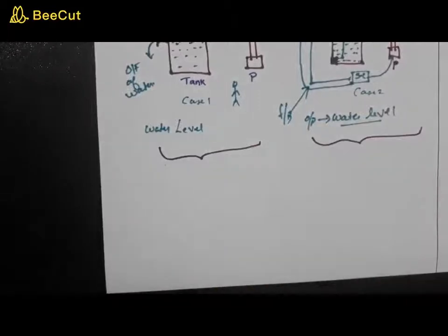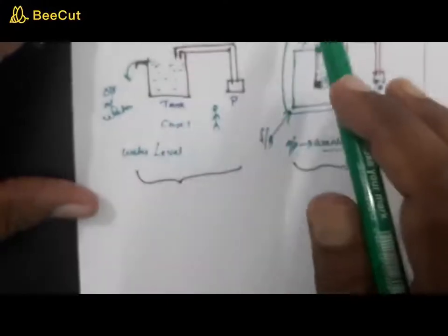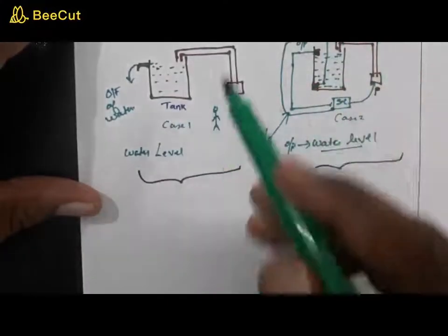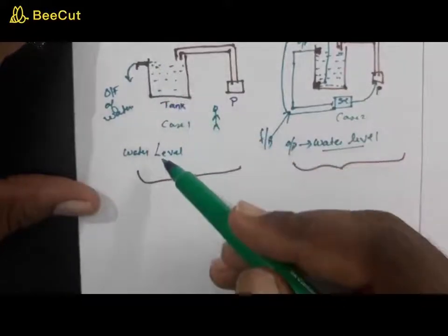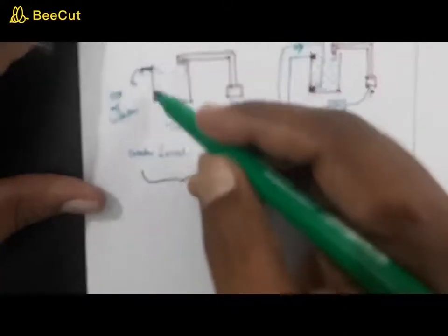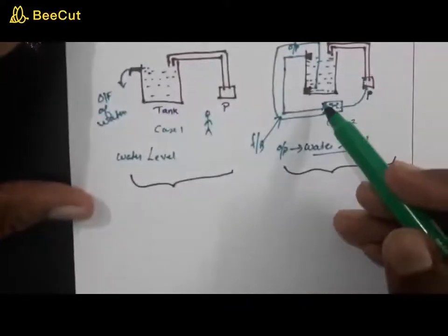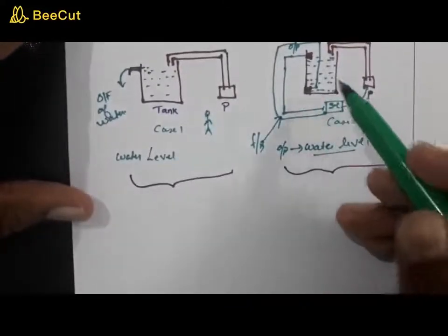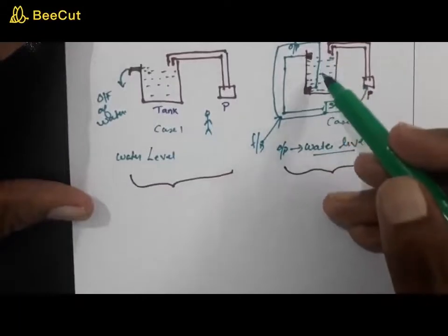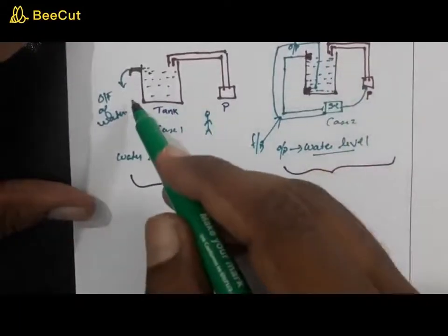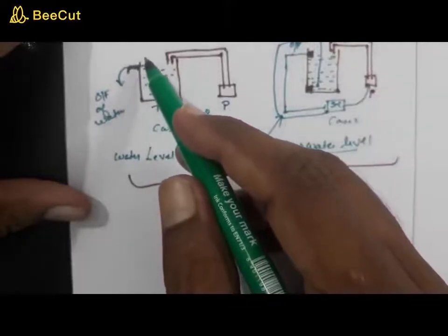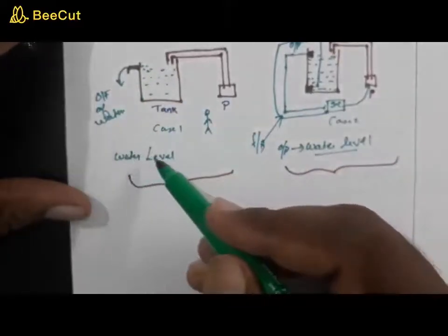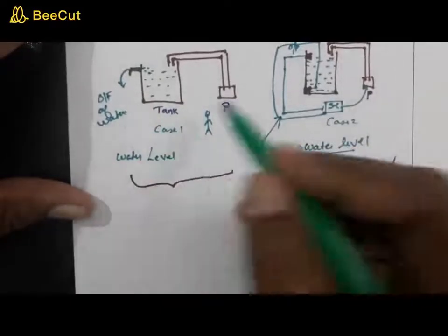Because in the two systems it controls. It is an arrangement of physical components to control itself or some other system. So it's controlling the water level, but that control action does not depend on the water level, right? While the control action that takes place here depends on the water level which is to be controlled. Since there is no direct relationship or connection between the output and the input, this is open, right?